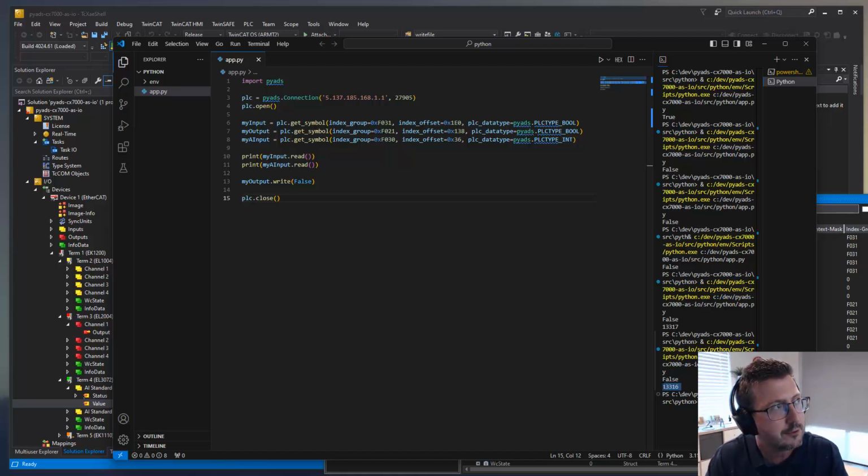would you use DC clocks? Would you use oversampled terminals? Probably not, because you are talking to it from a non-real-time system, which means you might lose data, as in you might miss data because it's not fast enough to keep up with EtherCAT. But if you needed to, then you would go just up a single level to a CX81 range, and then you'd be able to do absolutely any of the terminals that we support.